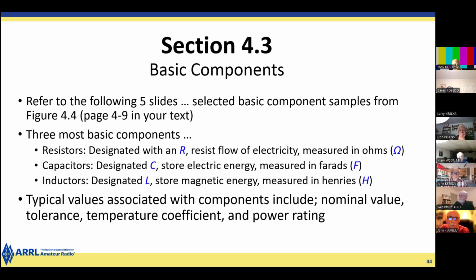Some of them are an eighth or a tenth of a watt dissipation rating. But if you were to plug in a light bulb to the wall socket and then put a resistor in series with that, that resistor would dissipate several watts. So you'd want a physically much larger resistor, and you'd need something to handle the heat also.